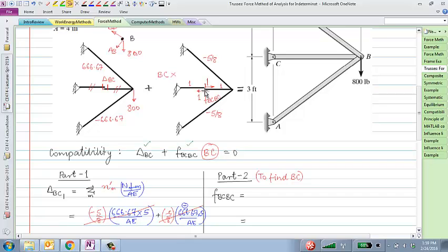Again, the virtual work method, right? Which would be basically that we take the virtual internal forces, that would be Nm prime, times the real displacement. But for this particular problem, the real and the virtual system is the same. And this also happened with our beam problem and also happened with our frame problem, right? The redundant system that we have ends up being the real system and the virtual system when we want to calculate flexibilities. So this is going to be a common theme throughout.